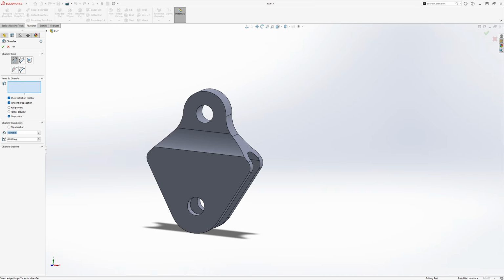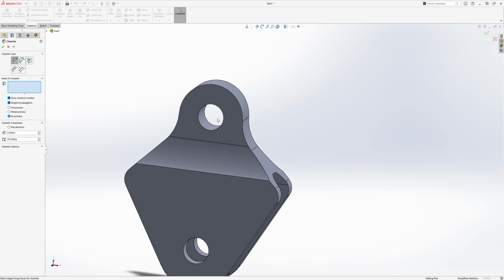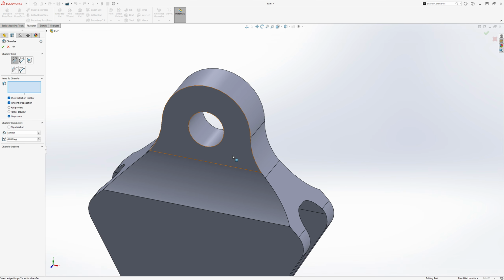In the engineering drawing on the section view, it says there are 4 5x 45 degree chamfers. So that means they're of distance 5 and 45 degrees. And there's 4 of them for the circles on both sides.